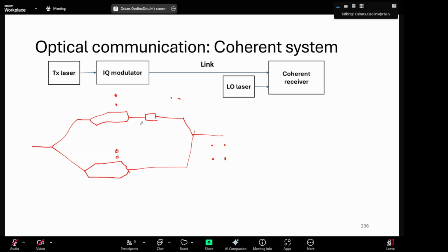Like in on-off keying you would have one bit per symbol, here we have 2 bits per symbol, because you have one symbol here and one symbol here. It is the same symbol, but you can represent 2 bits. We will look in more detail at different numbers of bits per constellation size. But let me just clean the screen.